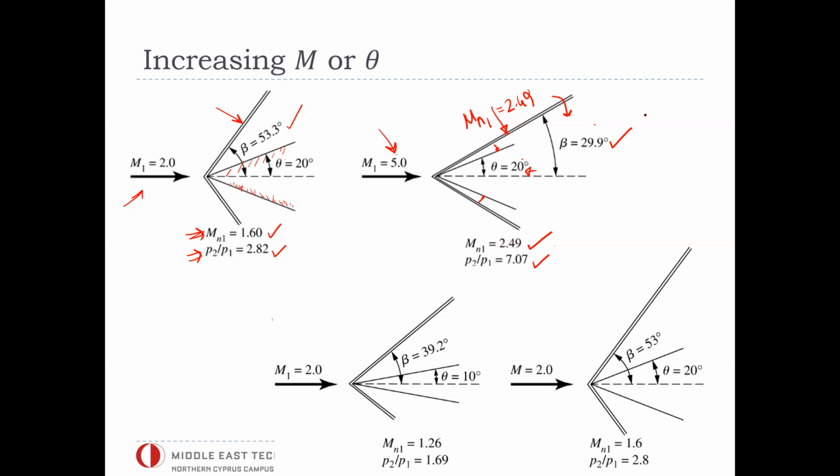If you remember Cp from Aerodynamics 1, the pressure coefficient on your wing has a definition: local pressure on the wing minus P infinity, divided by the dynamic pressure. Now, this P infinity will be 7 times higher than your atmospheric pressure before the shock wave.